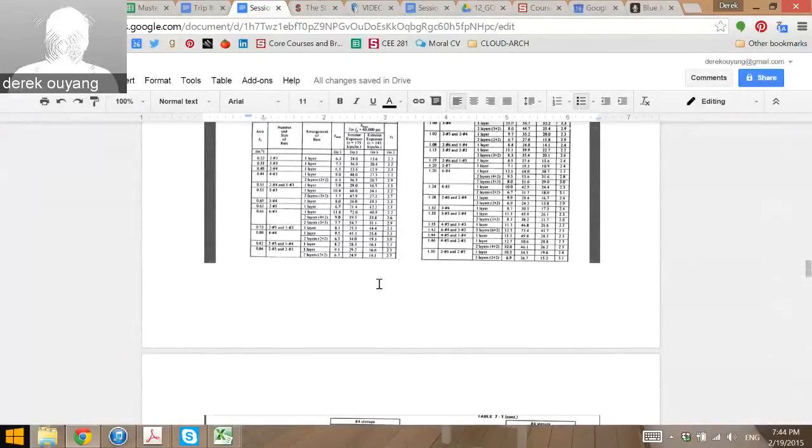What are the major things we talk about in concrete design? Let's assume just tension reinforcement. Let's first look at an exercise of just a rectangular beam. So we're talking about tension of steel, compression of concrete, right? And all this really is a moment capacity where this is the couple arm. You guys have figured out, obviously, that where this comes from is an approximation with the Whitney stress block. That comes from the stress diagram at some point looking like this, and it's crazy, so you just approximate it as that, where the amount of this is 0.85 of f'c.